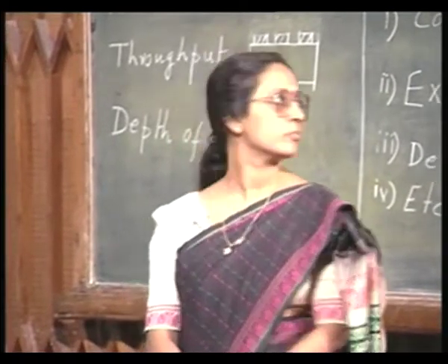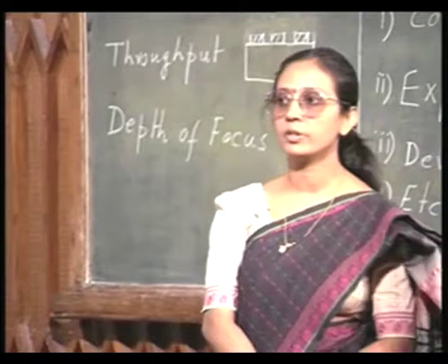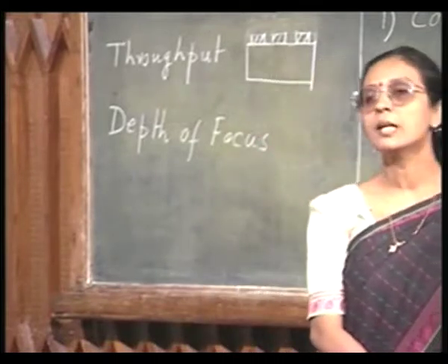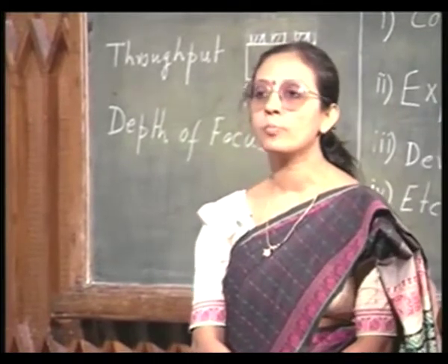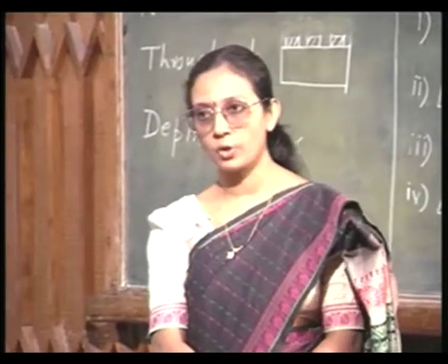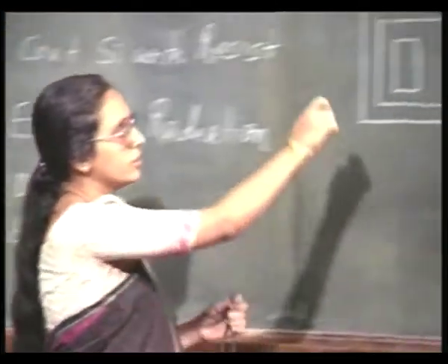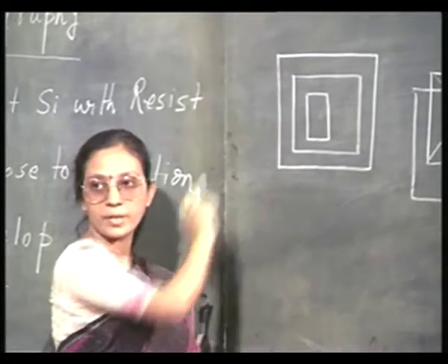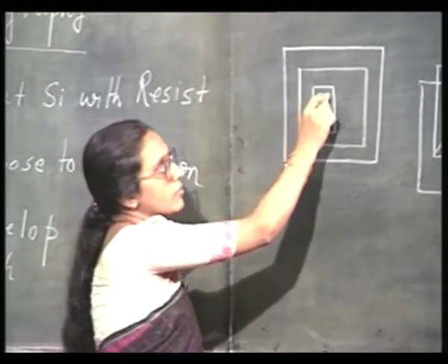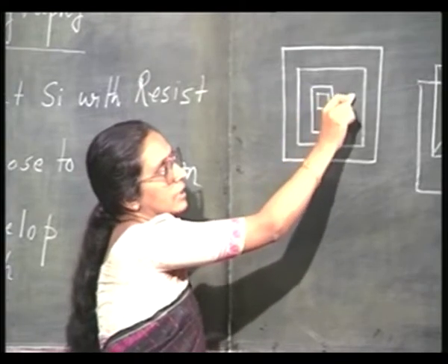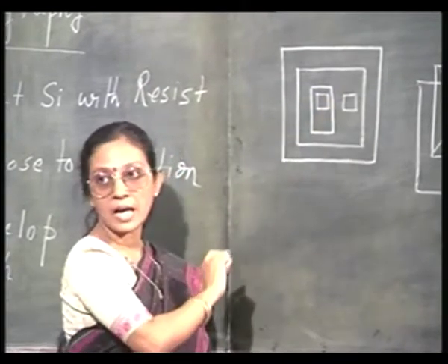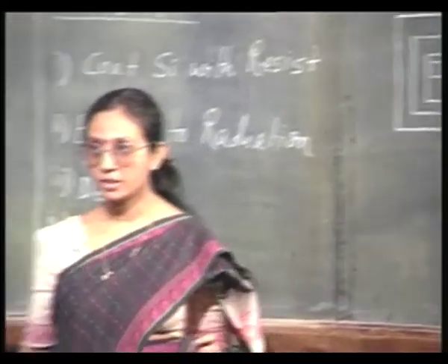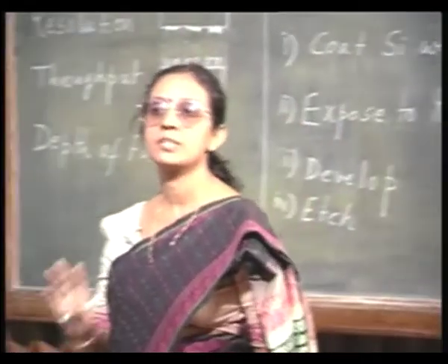First of all, like I started to do for this bipolar junction transistor, you complete the composite mask drawing. That is, I have defined the active area, I have defined the junction isolation, I have the base diffusion. Now, I must have the emitter and the collector pocket and then the contact metallization, etc. So, this is my first step.